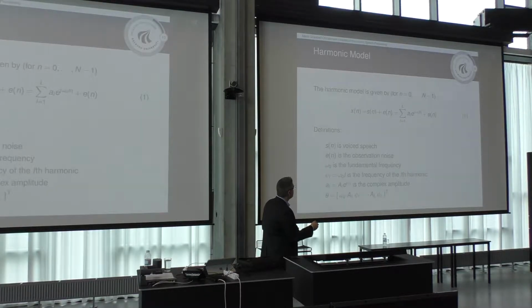And then we have the noise. So S is the voiced speech, E is the noise. Omega 0 is what we call the fundamental frequency or pitch, and then the frequencies are L times omega 0. And we can stuff all the parameters that we might be looking for into this parameter vector here.